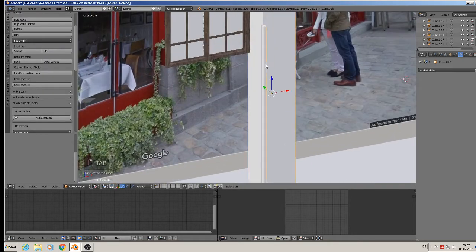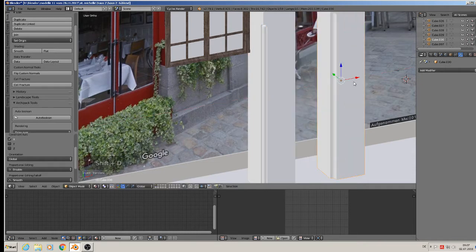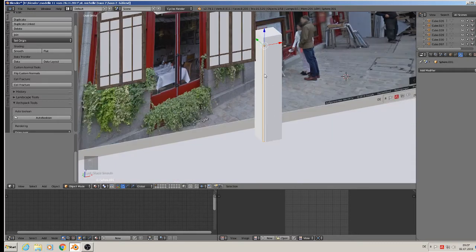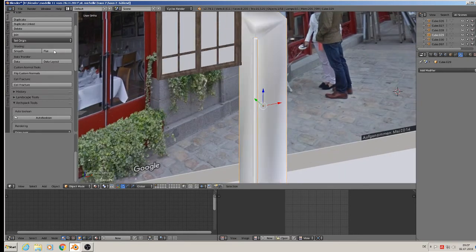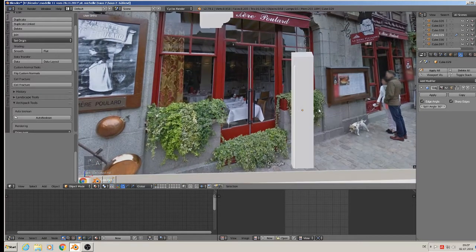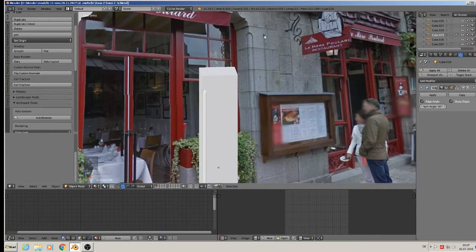Okay. Now we can make a copy of that, Shift D, and Shift D this part, and move that to the second layer, pressing M to move. Click on the 2 and it's moved. That one needs a smooth, and that here too. And here we need an add split on it, so we take modifier add split. Good. File, save.